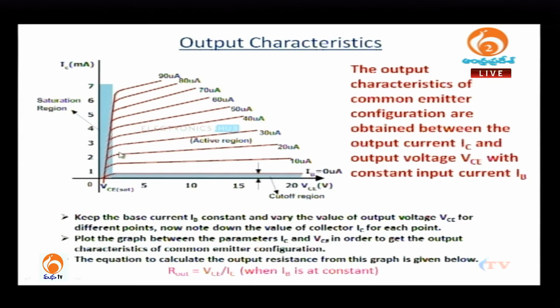Now, coming to another shaded region here. This shaded region represents the saturation region. Here you just see that a few tenths of a volt of collector voltage is applied. This will not be in a position to properly reverse bias the collector junction. For that reason, when collector voltage is increasing, proportionately we are having a collector current increase.